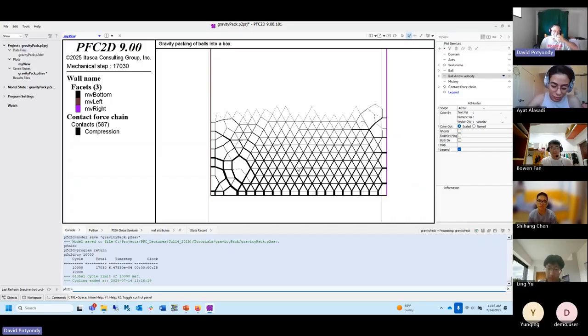So this is the idea of static equilibrium. This is fundamentally important in all of these runs. And so we've got damping on here. We've got high damping, which is making it eventually stop bouncing around. And then they've got this vibration happening of the particles, and that's slowly getting removed. We're getting a stable assembly. The force chains are showing us that it's essentially stable in carrying its forces. And so we're going to be using that solve ratio average. And 1e to the -5 is probably about enough for the vast majority of systems.